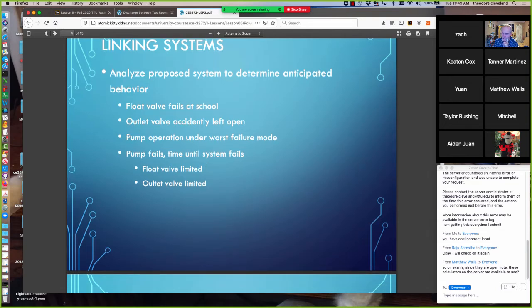So presumably the worst failure mode would be the pipe breaking. That's the 24 liters per second. What we discovered is that that particular pump that we specified isn't enough; we need almost 3 of them in series to handle the worst case failure mode. Now the pipeline failings should be unlikely, but that's good to know. It means that we have to put some effort into the pipeline design, as well as some maintenance monitoring to detect failures before that happens.